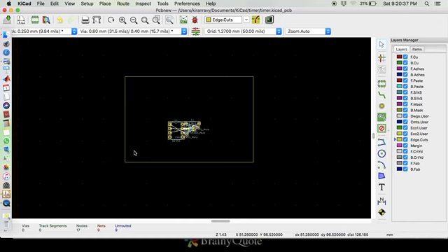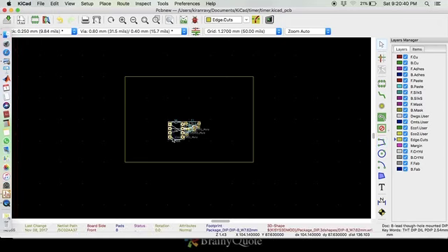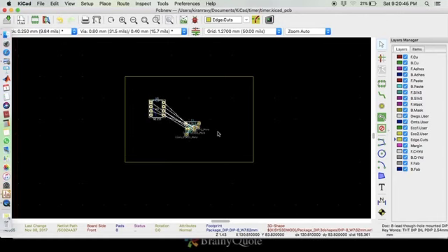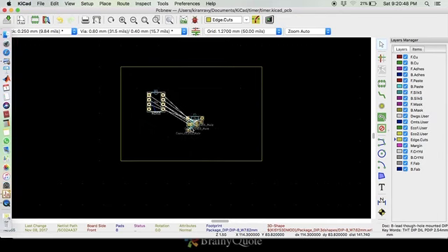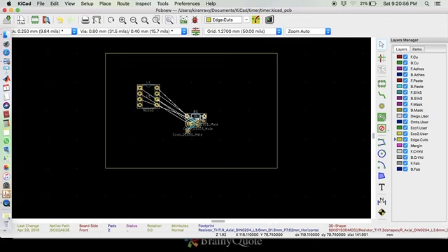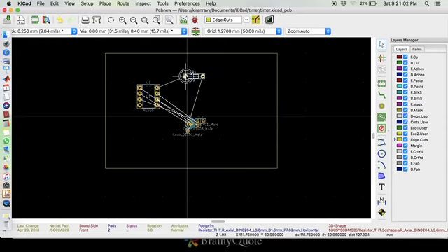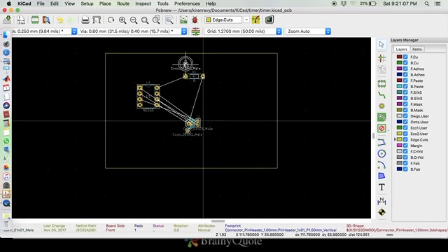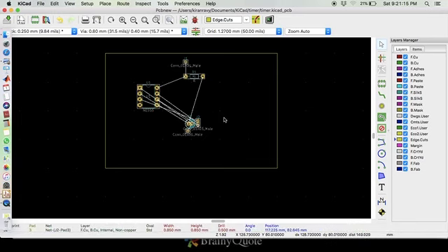So now click on this and select one component and drag it to some comfortable position somewhere in the board. See, this is just some kind of intuitive method. We'll just distribute the components to different locations, so that is okay. Now we have a connector here. So connectors usually will be there at the boundary of the board so that we can easily connect external components to it.